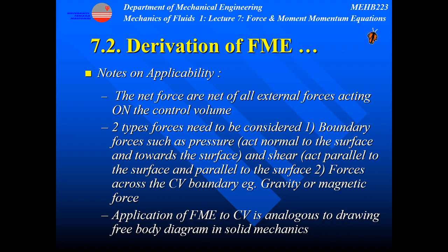There are some notes on applicability. The net force is the net of all external forces acting on the control volume. There are two types of force. One is the boundary force, such as the pressure force, which acts normal to the surface and towards the control volume, and the shear force, which acts parallel to the surface.